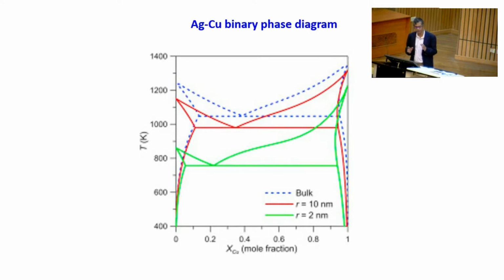And consider a more complicated phase diagram like this one, which is a eutectic phase diagram. You see there is a eutectic point here, between silver and copper. The silver-copper eutectic is a very important material for various purposes. Think of solders, at slightly higher temperatures obviously. Think of conductive materials, both are highly electrically conducting, or if you want to create different kinds of morphologies at nanoscale, this is one of the ideal systems to study and understand.